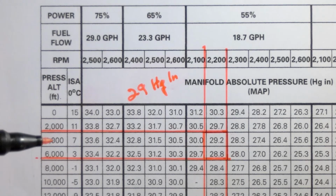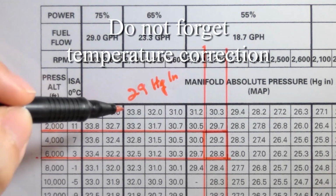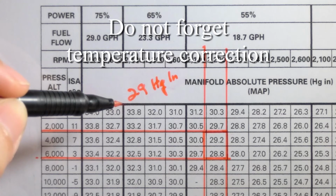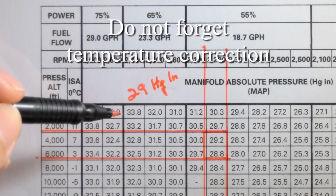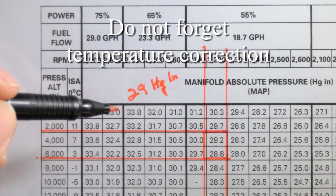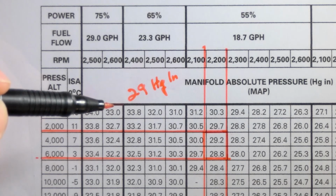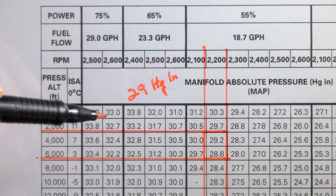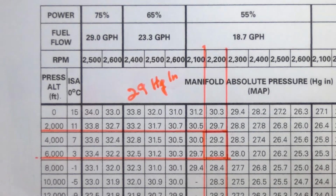The remaining thing to do is to make a temperature adjustment. That adjustment is either adding 1% or subtracting 1% depending on whether our ambient temperature is 6 degrees above or below the standard temperature. If our actual temperature doesn't differ by more than 6 degrees Celsius from standard temperature, then we do not need to make any adjustment. And that's how we use the power setting table, figure 3.3.